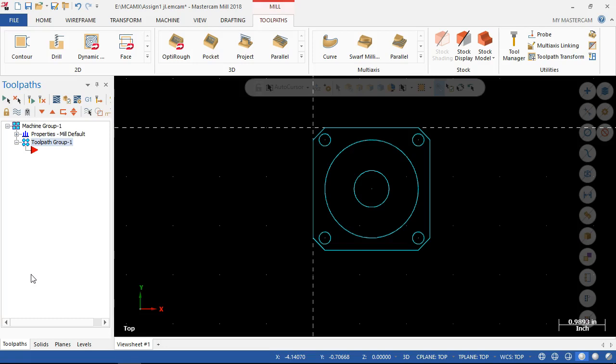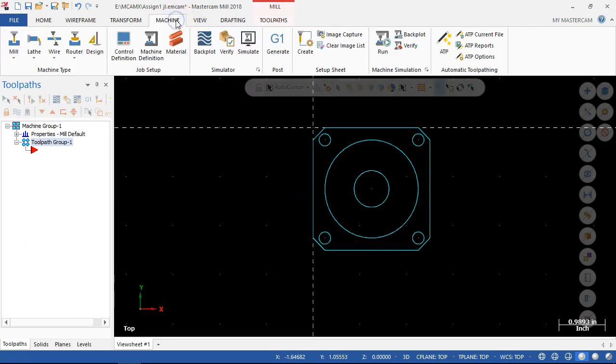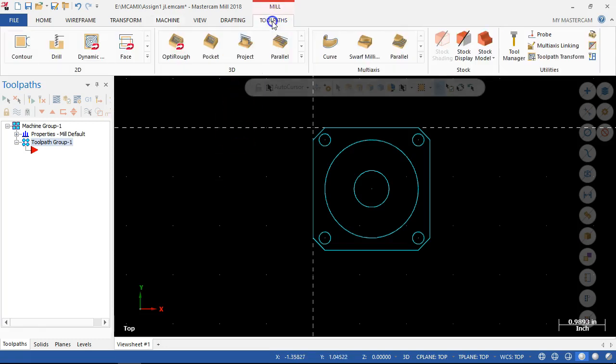There are some things that will go back under the control definition and the machine definition. There is a lot of information that we can set defaults for, like I want this information to show up in the header, I want this, and I don't want that. What I typically do is watch as I go through the process of programming, and if I'm changing things all of the time, every time, that's something I'm going to want to try and identify as a default that I can set in the machine definition and kind of jump over that step. Okay.